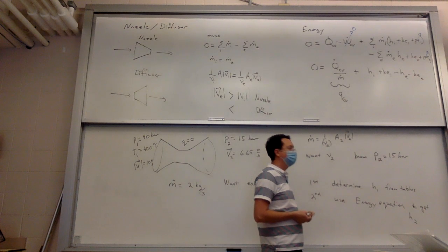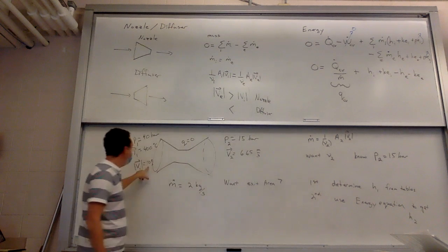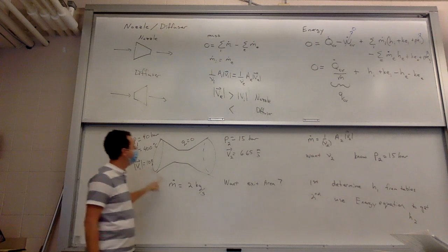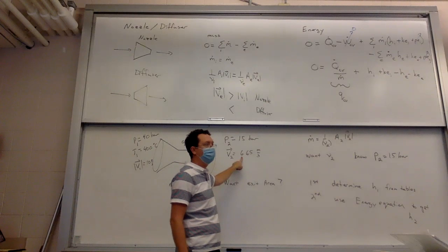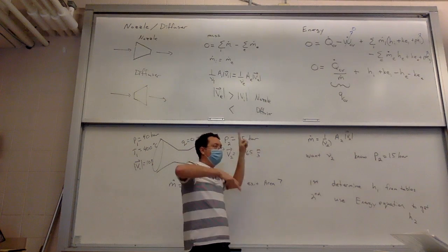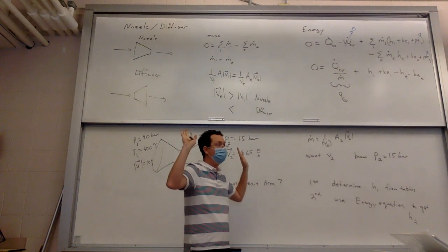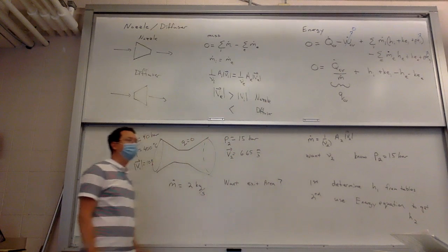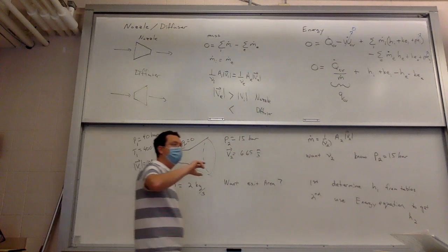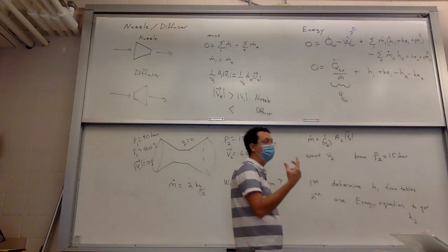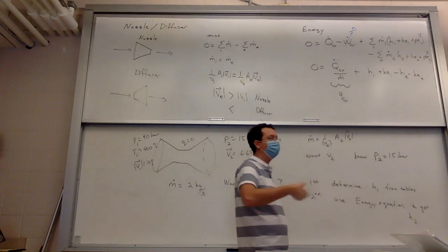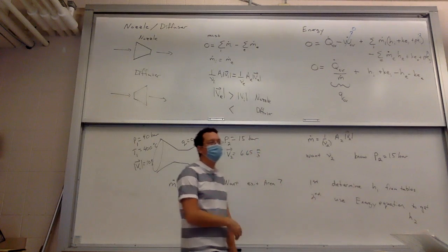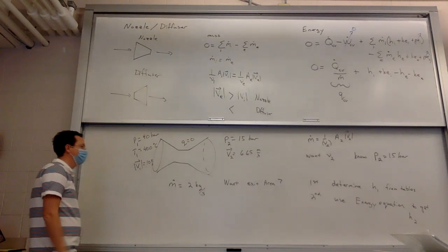Would the temperature really change that much from going in to going out? Well, the velocity has gone from 10 meters per second, 20 miles an hour, to more than 1,400 miles an hour. So the velocity change is extreme, and I don't have an intuition at that point. We're not talking about a lazy river. This is extreme, so the answer is I can't say. And it is also compressible because it's a vapor, a gas. A lot of your intuitions come from the garden hose, but you can't use the garden hose here. Figure this one out.